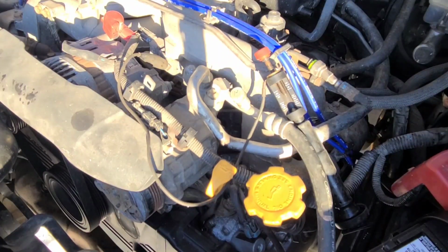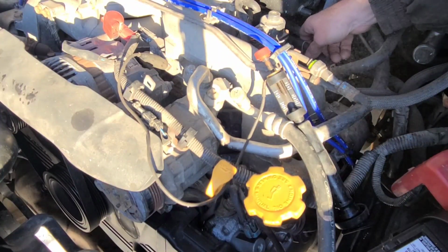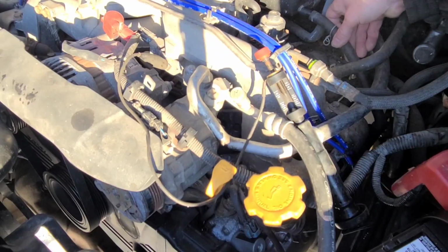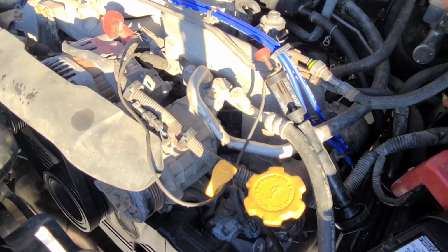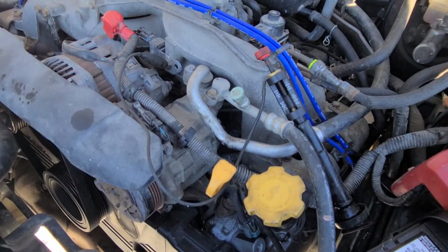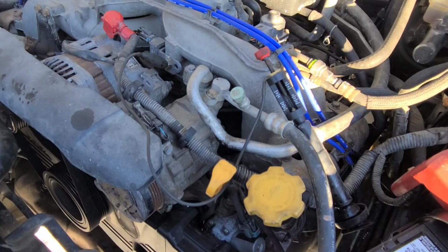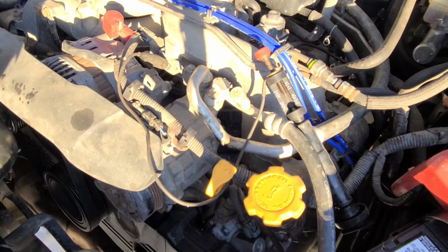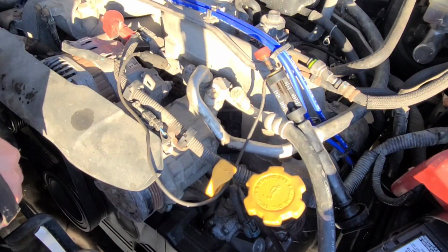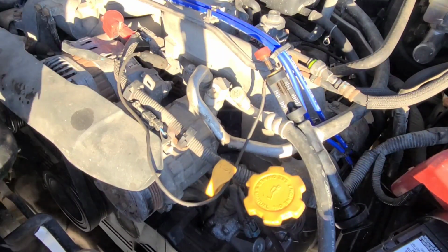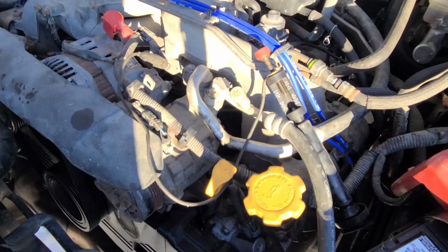How could plugging it in and warming it up make it start? I had an ignition trigger, I had power and ground to the coil. Got no spark, but I need to know if we got injector pulse. The scan tool showed injector activity. It showed RPM and a crank signal and a cam signal. Where are the damn injectors? I've got to get a trouble light out here.